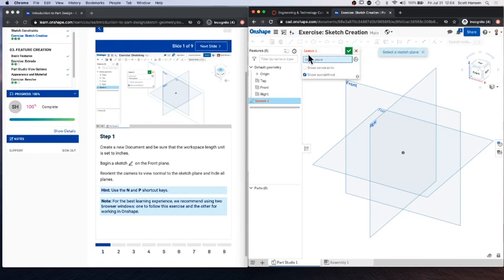Now you'll see the sketch 1 is red. We need to select that flat sketching plane to sketch on before we can actually do anything. And so the directions say to select that front default plane. The plane that you sketch on is going to depend on what you're designing, and you'll get used to selecting the right plane as we continue to create things. But I'm going to highlight this front plane, click that. Now I'm ready to sketch.